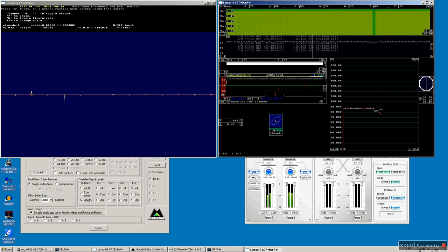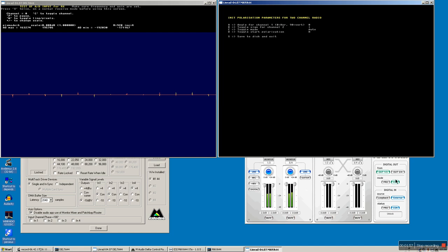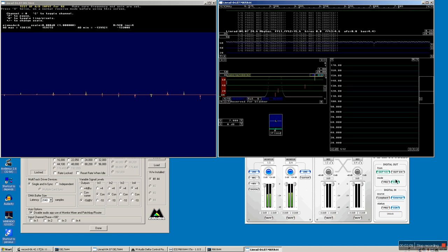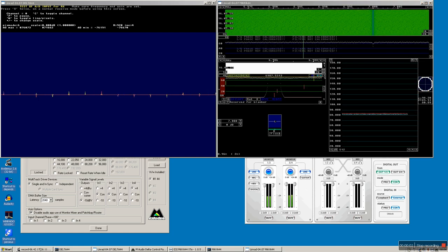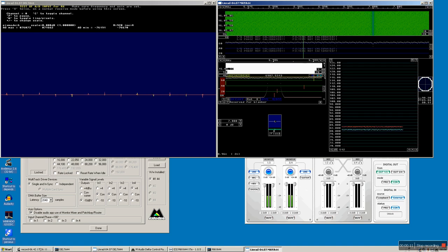And you can see very clearly, oops, now it starts to adapt the polarization. This was not what I wanted, so I make X and select polarization defaults and toggle mode, that is C, and then back, that is S, and then back. And look at the S meter again. And to see better, I make the scale expanded. It's the upgoing arrow.